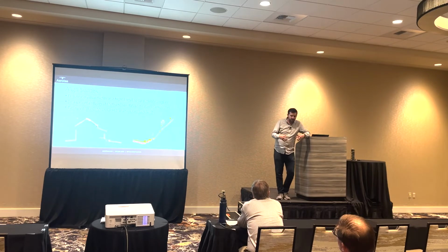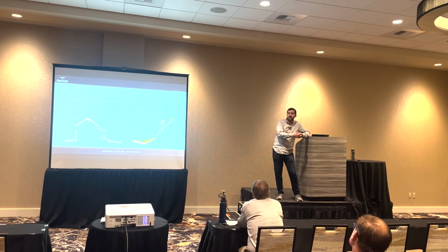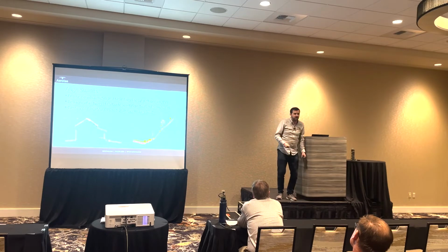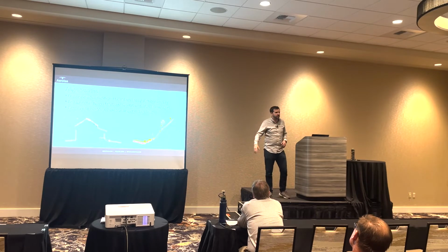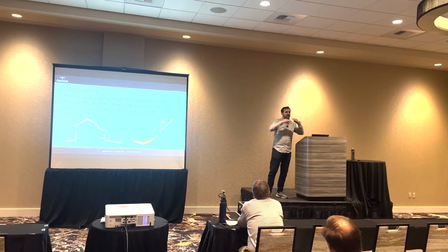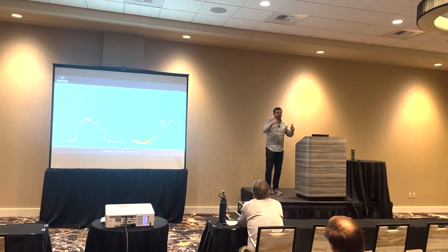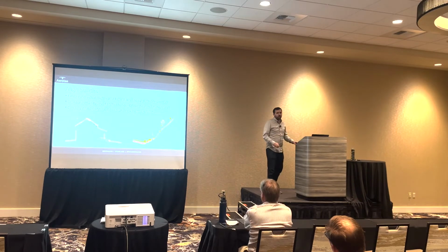We actually get OPUS solutions or similar on the DJI base station to get every single individual flight properly aligned, so that when we pick up our base station and move to a different takeoff location, we can correct it so that those all line up, and we can just get an OPUS solution offset from what the initialized position of the GPS was with the corrected position. And that gets everything to line up usually within 1/10 of a foot.